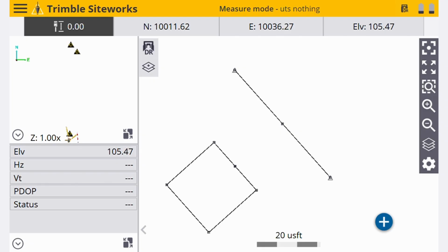Now, everyone calls an Alaskan slab something a little bit different, but we're going to make thickened edges around a slab. In this, I don't care about making the flat finish grade surface. What I want to make is my top of stone surface. So we have our box.